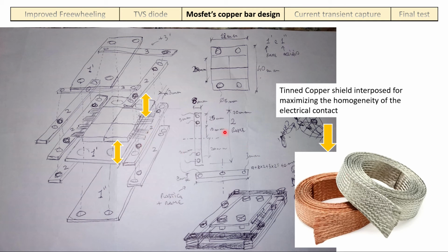More homogeneous current means better distribution of the power across each MOSFET. So there is no MOSFET overload and overall the performance is better. It's better to have a smaller number of MOSFETs than a lot of MOSFETs that are not well connected to each other.